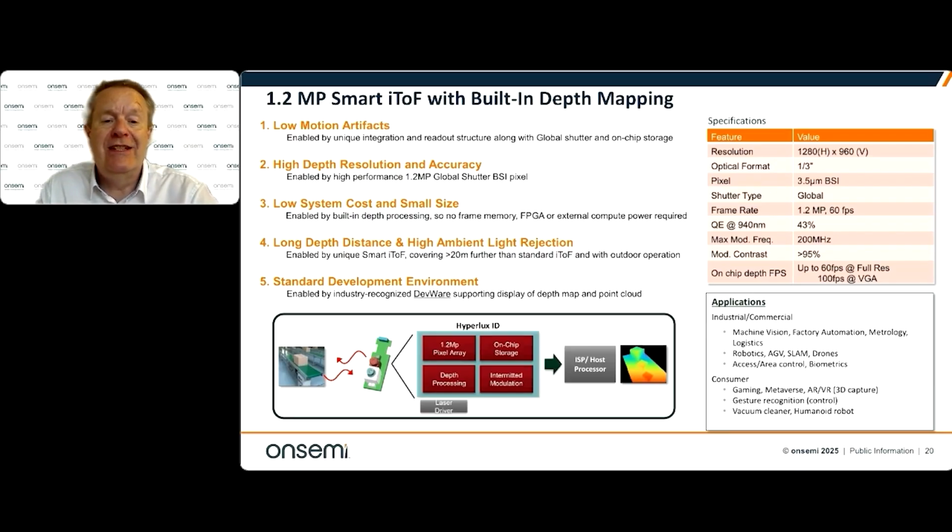Also, this uses a standard development environment. So if you want to evaluate this sensor, you can use the standard hardware that we use for all of our Hyperlux sensors. So we have a family of Hyperlux sensors, Hyperlux LP, Hyperlux LH, Hyperlux SG, all have headboards on the sensors, and our legacy sensors all had headboards with a standard baseboard that plugs through the USB into the computer. The development environment for that is called DevWare. So DevWare is renowned in the industry as the most flexible application software for pixel evaluation.